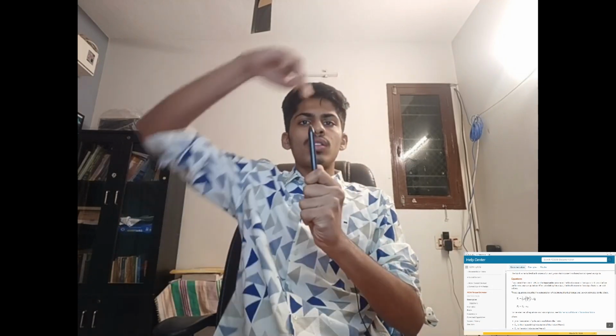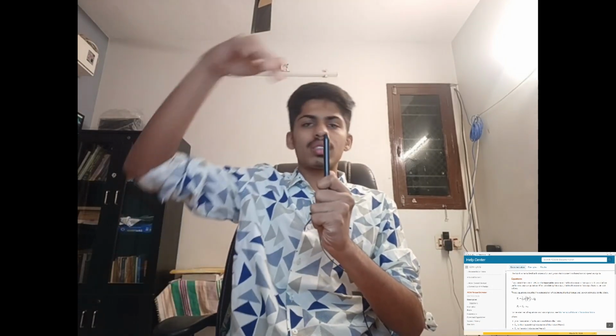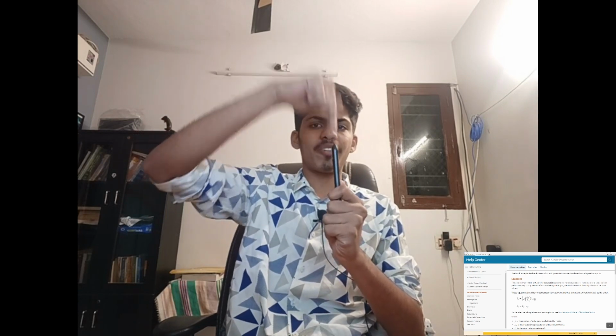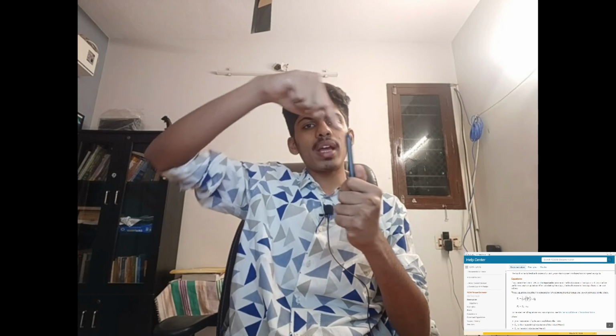So let's say this is our rotor. So this is our stator's current. So the stator's magnetic field we are resolving into two components. The direct axis component, which is flux producing component, and the quadrature axis component. If you want the motor to have high torque, that is high twisting force, you have to make this quantity, that is the quadrature axis quantity, much larger. So it will produce a larger twisting force.